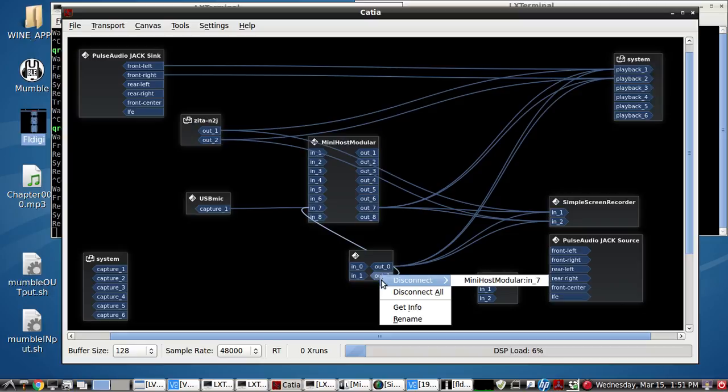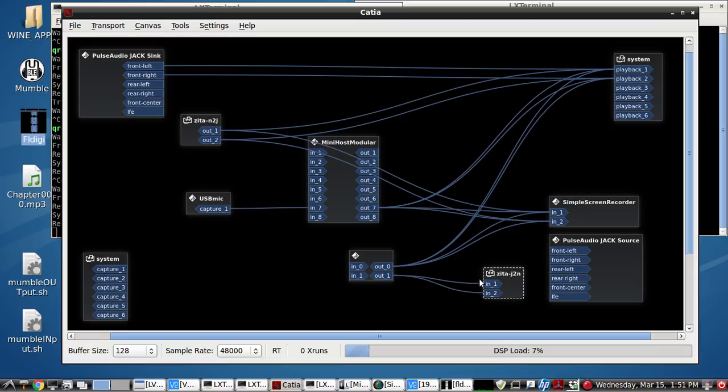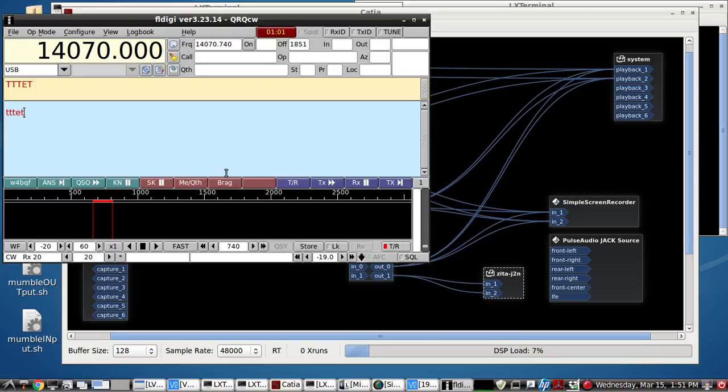So that upper tone is kind of a square wave, or it's actually a 1K hertz tone with no rise or fall time. It's at 0 rise and 0 fall, so it has a lot of key clicking. But that doesn't matter for the key switch circuit, the audio-derived key switch. So let's see. Send a QRL here. And you can probably hear the receive audio in between there, so it is working.